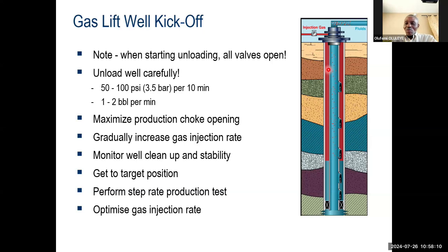Thirdly, are we talking of just one phase or two phase fluid, or do we have three phase fluid? I mean, if we have solids with the gas and also liquid oil in the wellbore, how do we handle the multi-phase fluid to ensure that we still have a successful operation? Thank you very much.